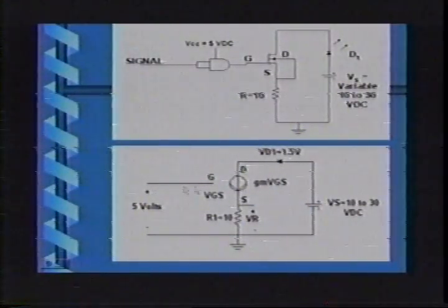If you look at the input loop, and I've shown this when the pulse train is positive at 5 volts, looking at this loop, you have 5 volts at the input. You have 1 volt as the given voltage between gate and source, so you can easily find with a loop equation that the voltage across this resistor is 4 volts.